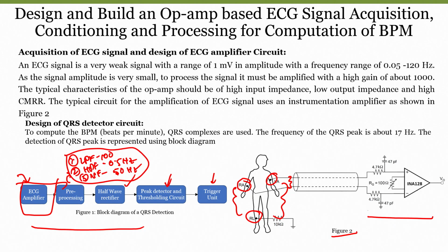And if I connect that to some kind of counter which counts only when I get a high peak, then it gives us a complete indication of beats per minute. So, in 1 minute the number of peaks that we get indicates our BPM. If I can do all these conditioning circuits and processing circuits using operational amplifiers, it will be very great.